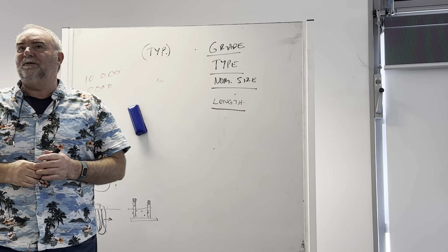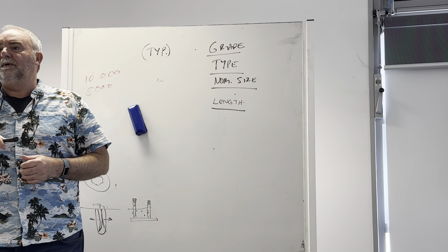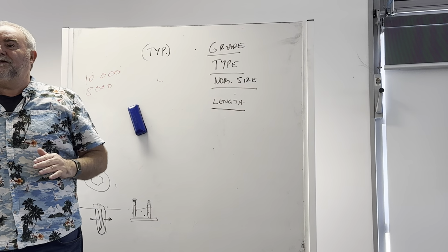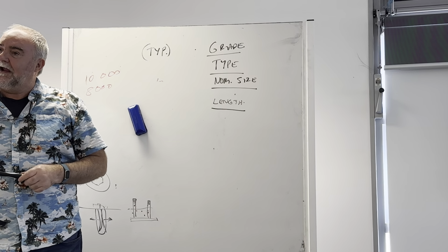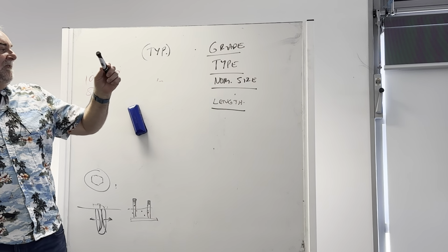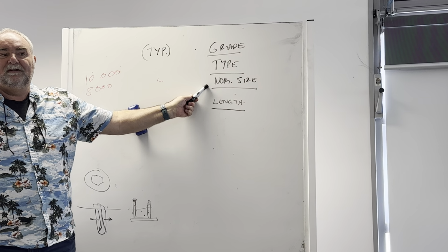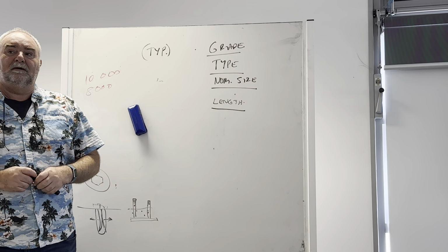And of course, when you're a structural engineer, you're doing calculations for the area of the beam, and if you keep losing 5 mil all the time, you're getting your calculations wrong. So you should always do the calculation on the actual size, but the call up on the drawing is the nominal size. So there is a difference, and to a structural engineer it can mean quite a bit.